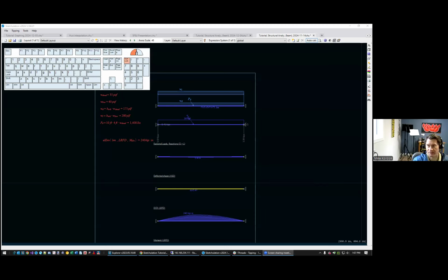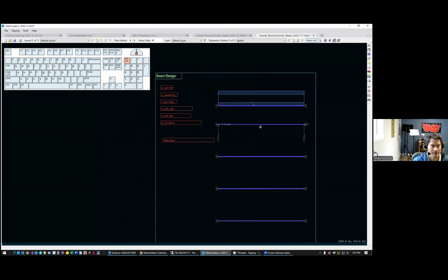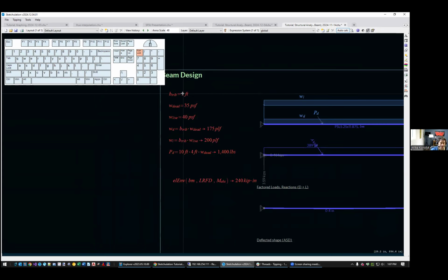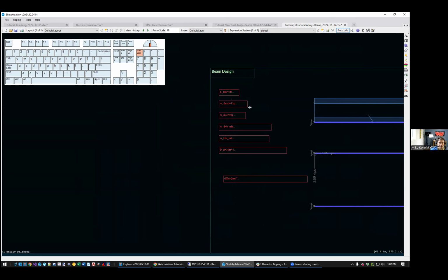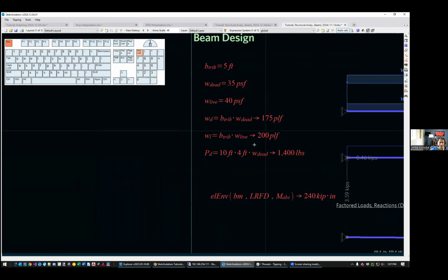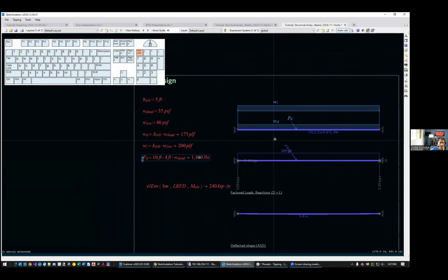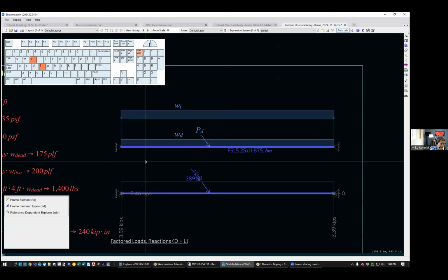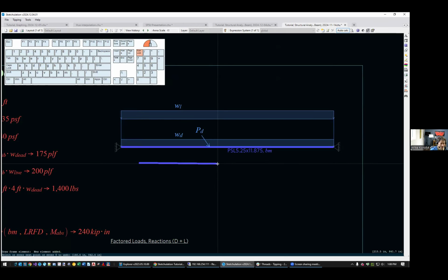Okay, so by way of review, we'll go back and take a look at what we had done before, which was structural analysis in Sketchulation. We showed how you make expressions to define the loading first, so the tributary width and then some dead and live load, and then we used the trib width and these pressures to create our linear loads, and then we made a point load, and then we defined linear loads here that we put on our frame element. Frame element, FE, was the command to draw a frame element, so we can draw that in there like that.